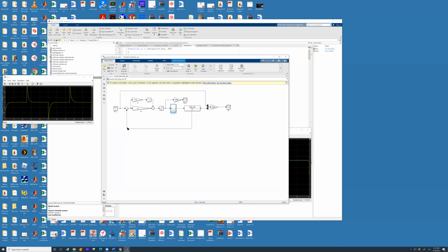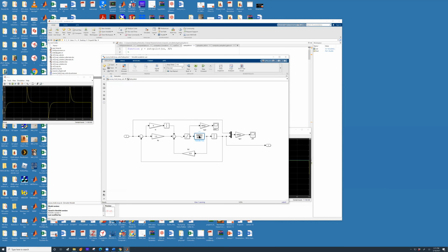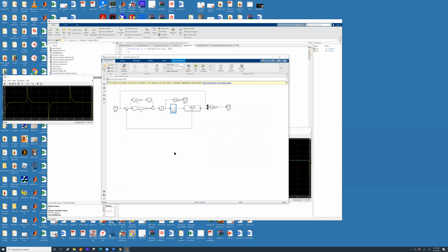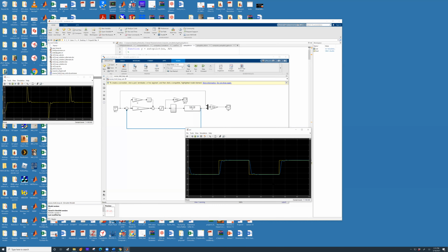And if you look at the course heading or the course hold loop, it comprises the outer loop. Now, please understand, you have to implement this for Zagi. These coefficients that I have used in this numerator and denominator are sort of arbitrary for Aerosonde. You need to implement this loop for Zagi. Any questions here? And then you should run this loop and observe what happens.